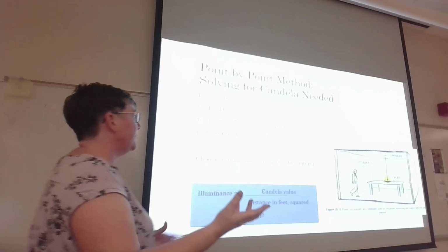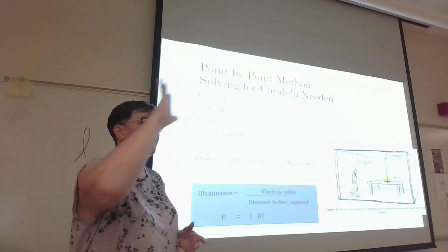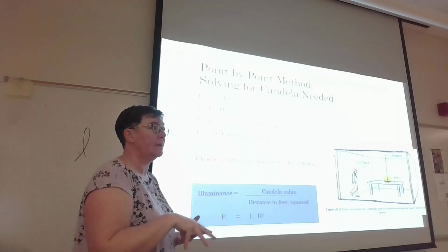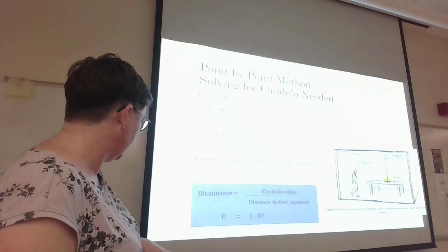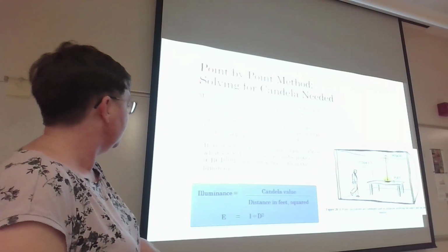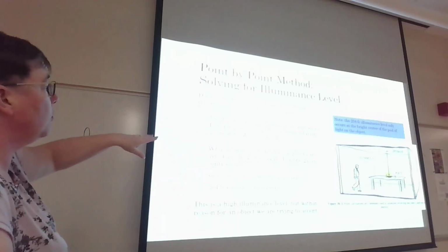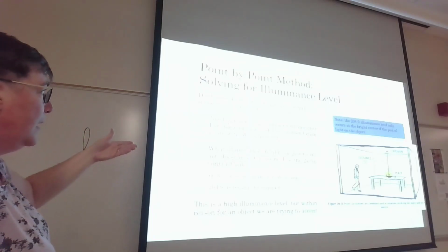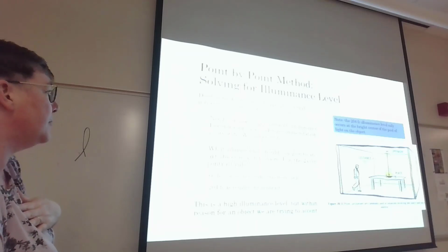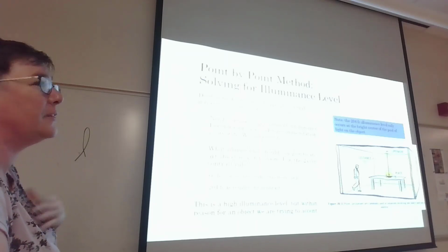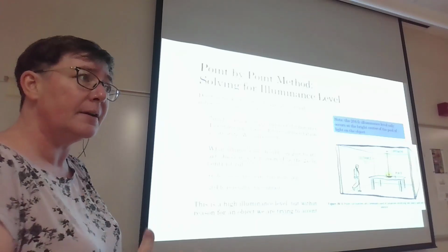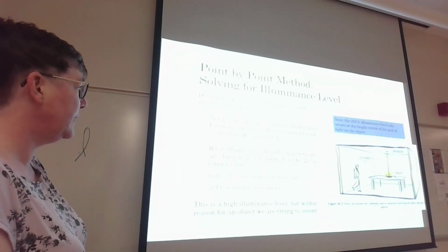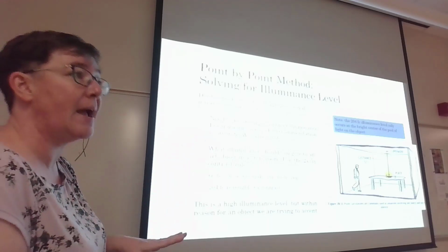So you as a lighting designer decided that you wanted 5 times the ambient illuminance of the room on this particular art plate. Let's go back and set this question up. All right. So the IES recommendation is 30 foot candles, or 30 to 50. We decided 30. And then with the last example, we found that light created 204 foot candles. That was 6 times contrast, and we decided in our design that was too much. So what would give us 5 times contrast? What would give us the 150 foot candles? That's what you're now calculating.